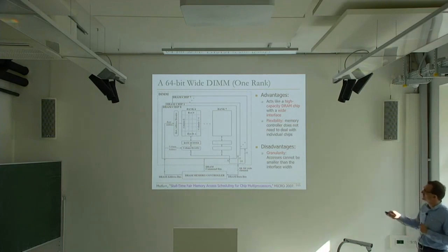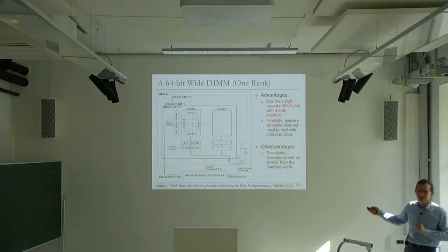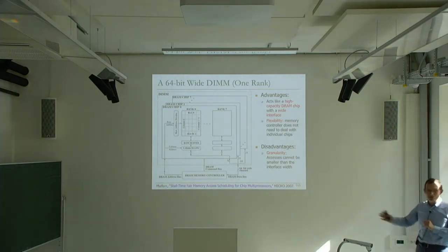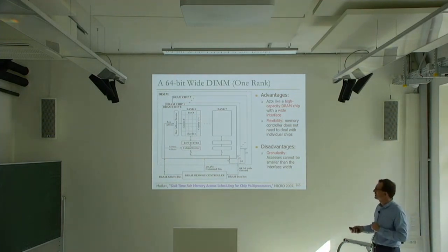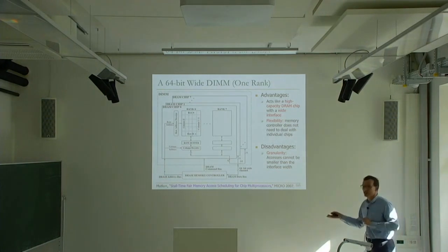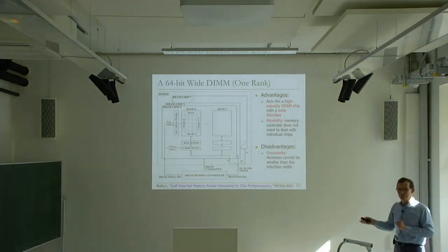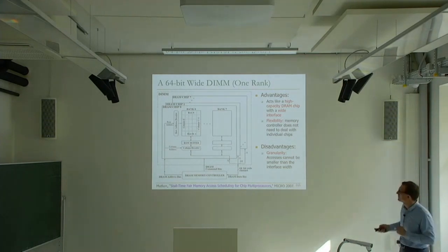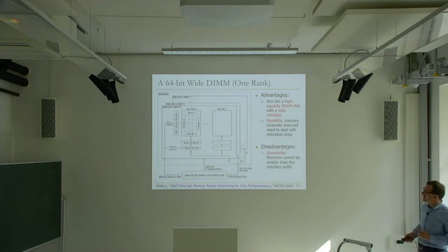I think going forward, actually, figuring out the solution to this granularity problem is going to be important. And people have shown that you're wasting a lot of power whenever you're doing random access to 8 bytes, for example. You really need 8 bytes, but you're fetching 64 bytes. So by definition, you're wasting 87.5% of your memory bandwidth. Right? OK.